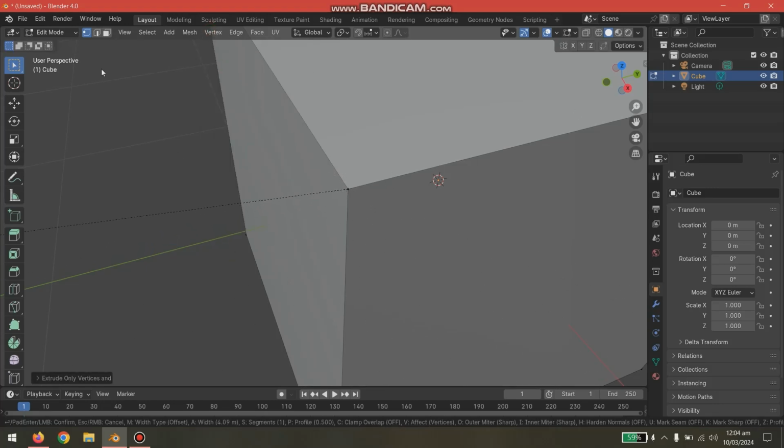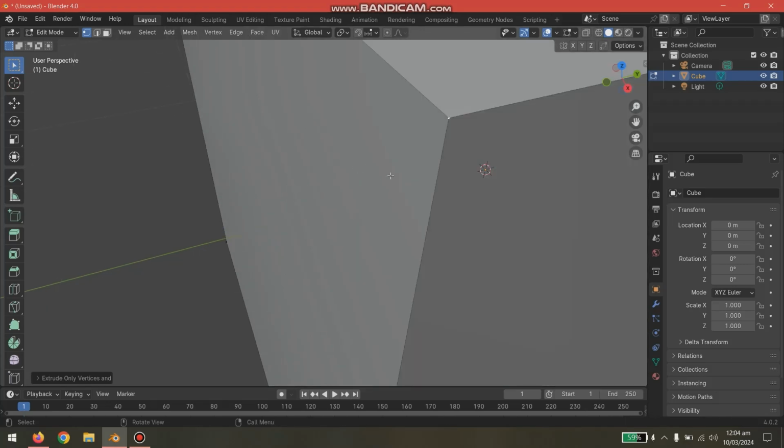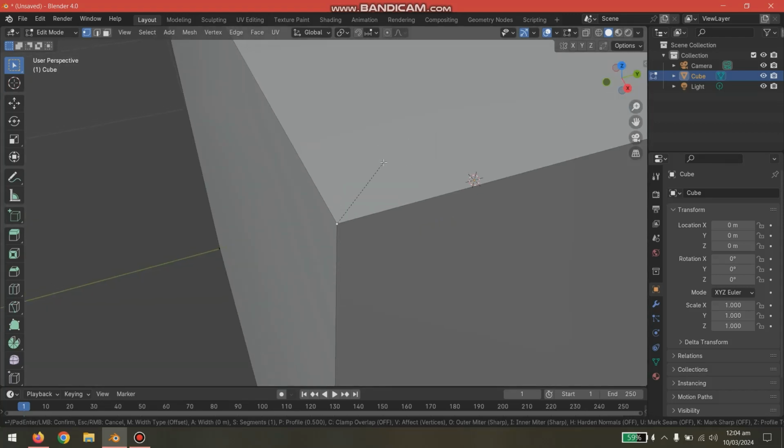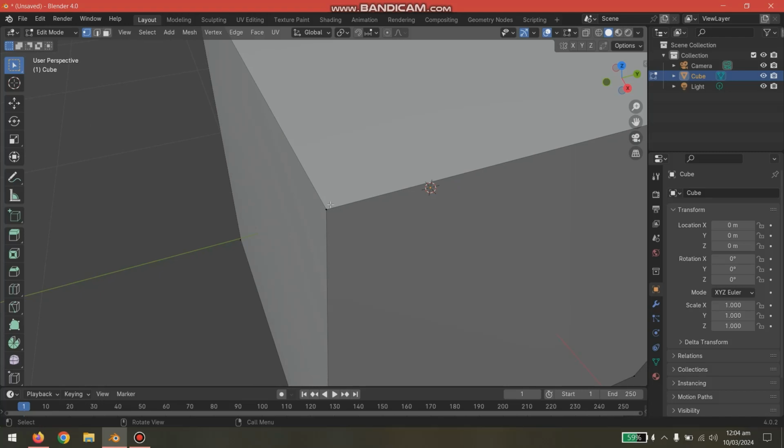You can see here it takes a lot of time and it wastes your time. So it's better to just use the shortcut. Select this vertex, zoom in a little bit, then Control Shift B, and try to do it yourself. So if you press Control Shift B and you do nothing, just press Control Shift B and leave it. So the bevel is there, just not clearly drawn.